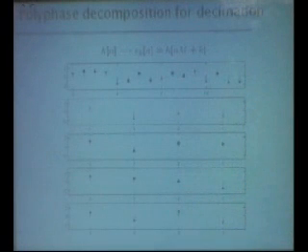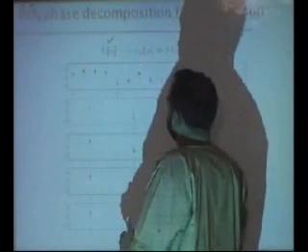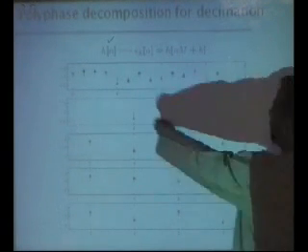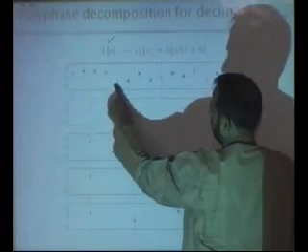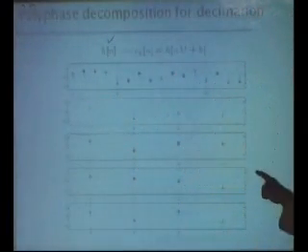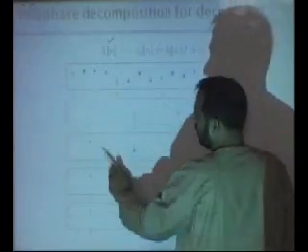So you design a pi over M filter. Once you have this filter, the polyphase decomposition requires you to decompose this filter into M filters, and we'll see why we are doing this. For example, this is my h of n, and these are the different samples of my decimation filter, which is designed by using the MATLAB command FIR1. Now I decompose it into M filters.